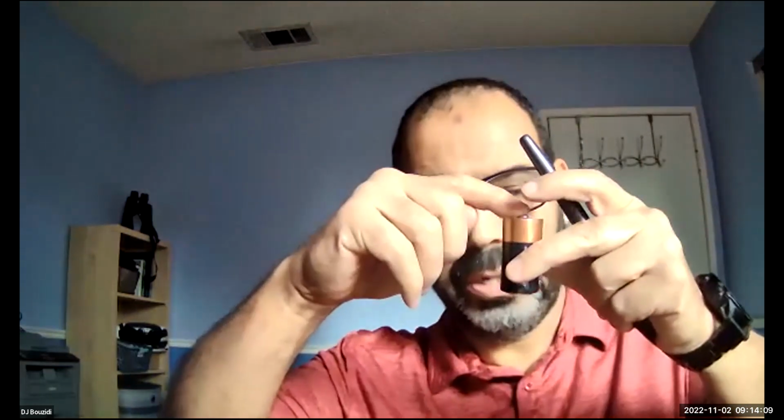So in this case, we are interested in actually how big this potential is compared to this potential. We don't care what this potential is. We don't care what this potential is. We don't care at all what they might be. This will be a billion. This will be a billion and 1.5 in addition to that billion. That's a 1.5 volt battery. If you have this one is negative 12, this one is negative what? 10.5. So if I subtract negative 10.5, deduct from it negative 12, I will end up with again 1.5.